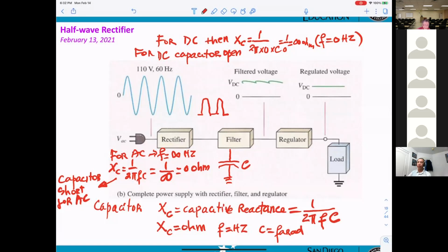Now when you're looking at the output of the filter here, it looks like that one, and then goes to the filter. Basically the capacitor will be charging up. That means it starts at 0 here and charges up to the point right here. That tells you the DC voltage. However, on top of that DC, there is this signal here. Well, what is it? A ripple.